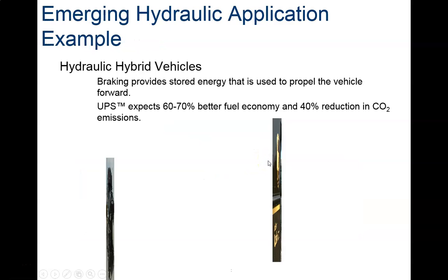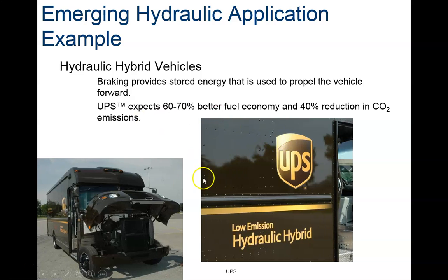So this I never heard of before. This is a hydraulic vehicle. And basically, I looked it up. I didn't find too much information on it. I didn't try that hard, but it looks like it's another regenerative braking system, which basically means the energy that you normally would lose by applying your brakes and converting the energy into heat, that energy gets stored in a pressurized reservoir, and is available when you speed up the next time.